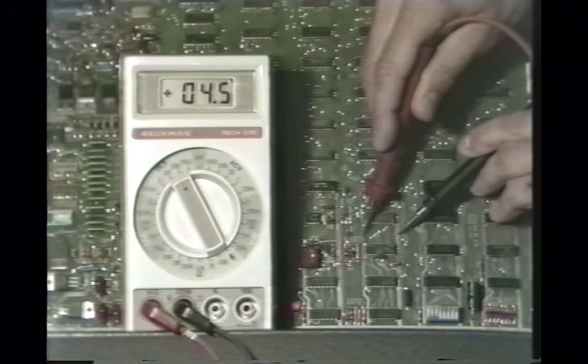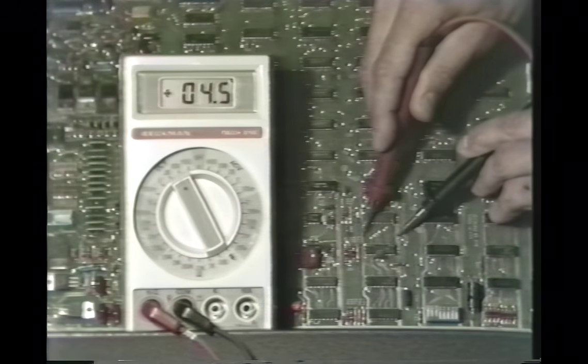That's because the meter is averaging the times when the voltage is up at 5 with the times that the voltage is allowed to drop lower because of that defective filter capacitor. The meter averages out the two and shows us a reading of 4.5 volts. Although the meter shows us a reading that seems to indicate our problem is a low voltage coming out of the regulator, we know that our problem is really caused by a bad filter capacitor.